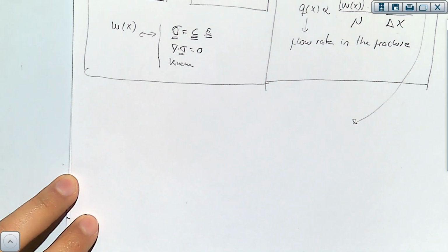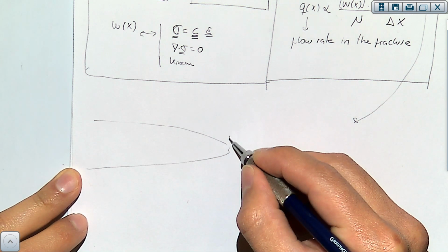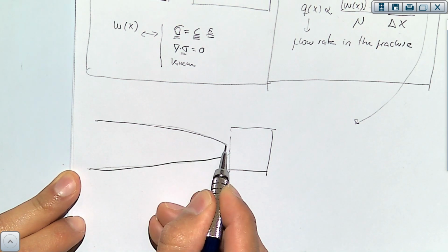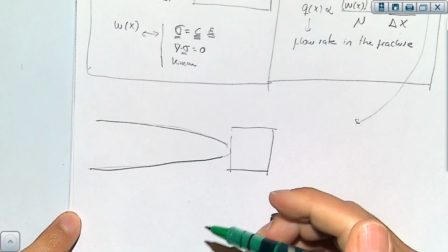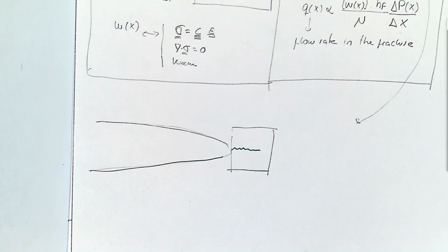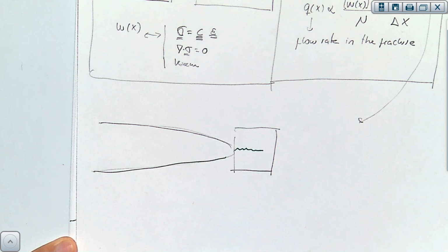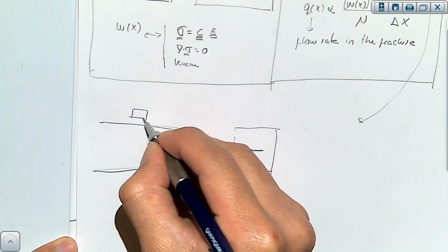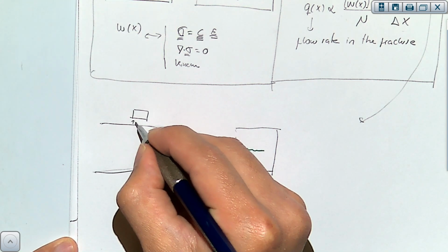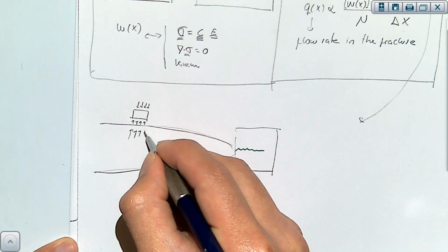And that new rock surface, let's make a zoom. This is a fracture. We're looking at stresses at the tip of the fracture. As this one propagates, this is how the rock is going to break. Here, let's say, if I had an element of rock very close to the fracture face, I'm going to have compression because the fluid is pressing against it.